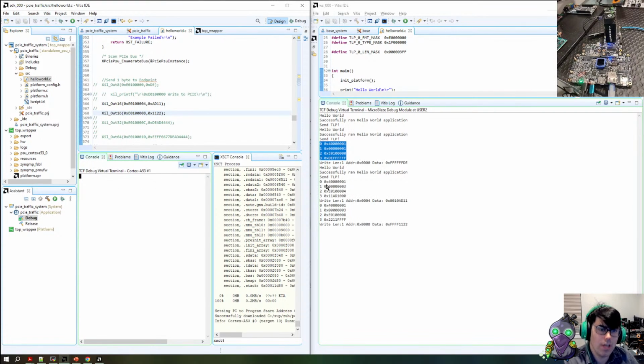Okay. So now, once again, we have a write 1D word. We're going to be doing 2 bytes, so that's your mask right there. We're looking at 2 bytes, and the address has changed a little bit. We have different offsets here, and then we have our data, and we have to assume everything after the data is garbage because these are all Fs, and that's a 100. So those are 2 byte packets.